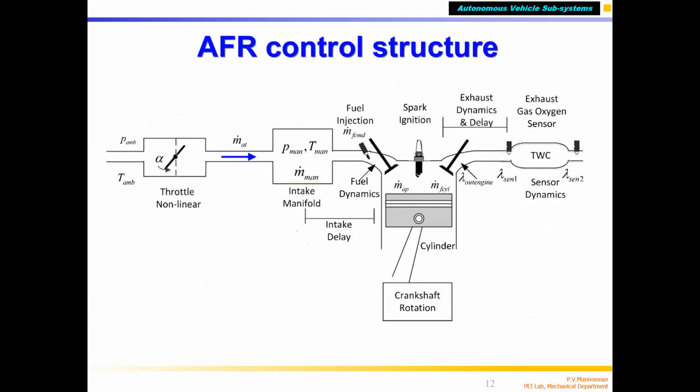So now this mass entering, fuel injected, when you give a spark, combustion happens. Once combustion happens, at the end of the stroke, the exhaust valve opens. This is the exhaust valve, correct. Valve opens, the hot combustion gas just goes out, correct. So here you are measuring the lambda, air fuel ratio, correct. Air fuel ratio, AFR. How are you measuring? Using EGO sensor, exhaust gas oxygen sensor, which measures the lambda, air fuel ratio, whether 15:1, whatever is happening, correct.